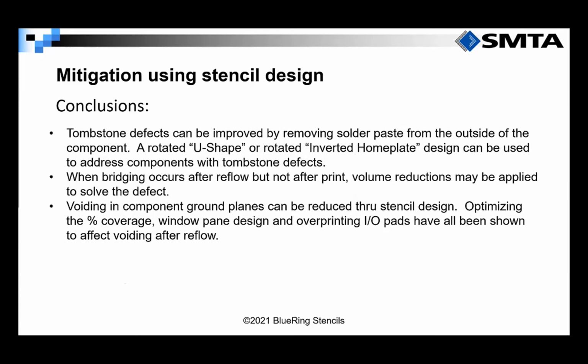And one way we can do that is with the use of a rotated U-shape or rotated inverted home plate. And in some cases, you may have to just remove solder paste from the back side of those pads if it's a very large pad and you're replacing a smaller part on it. Then we looked at bridging and how bridging occurs after reflow but not after print, what we can do and what we can look for to try to resolve that defect.